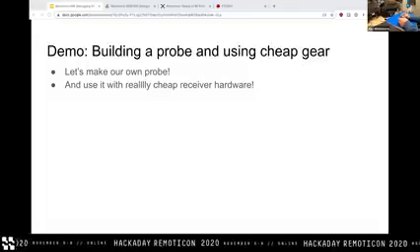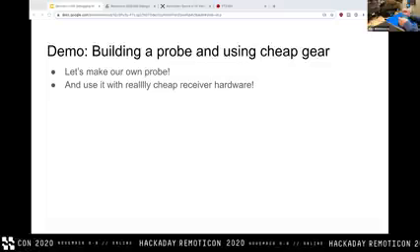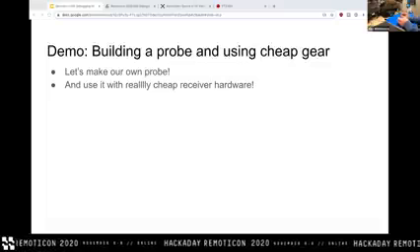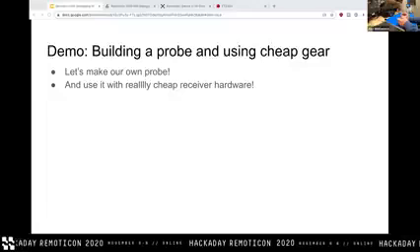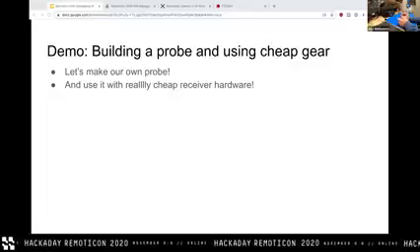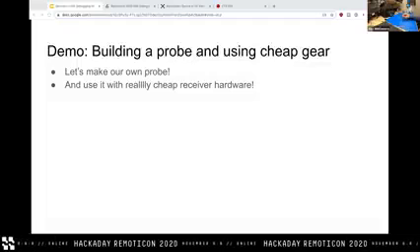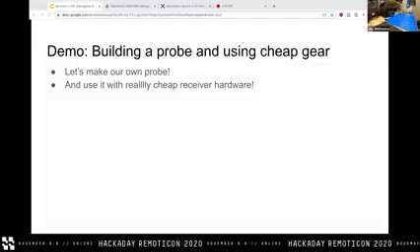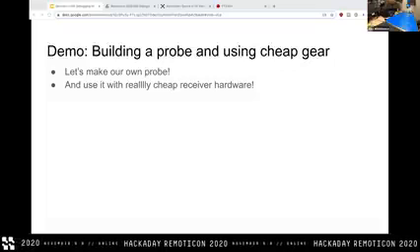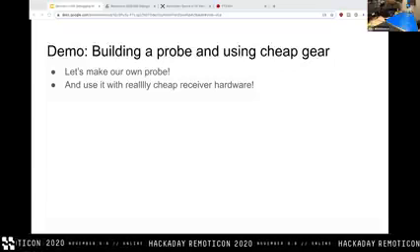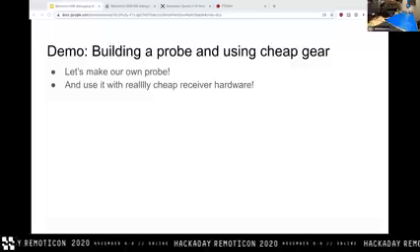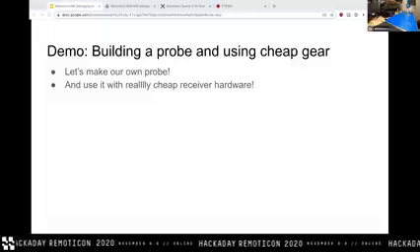So effectively, if you plug this antenna directly into the bias T enabled SDR and you have no way to turn the bias T off, you're just pulling tons of current out of the bias T. This SDR device can handle that for a brief period of time, but you basically overheat the linear regulator that powers that circuit, and after a few seconds or something like that, it will eventually burn out.